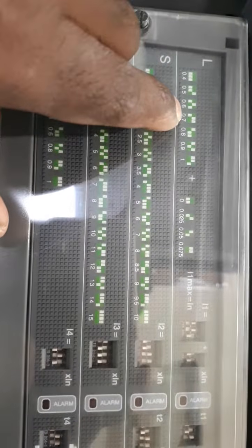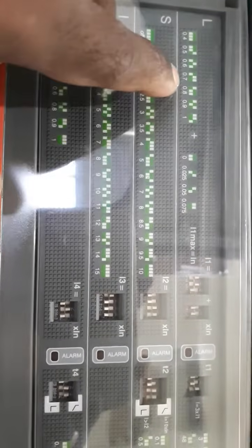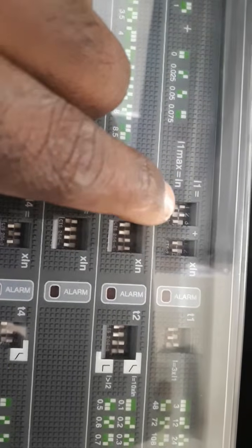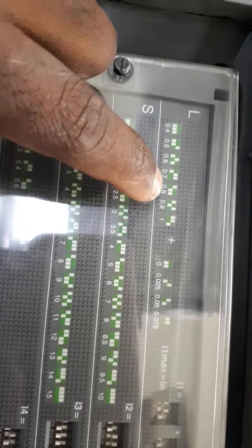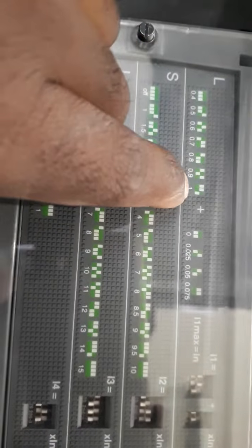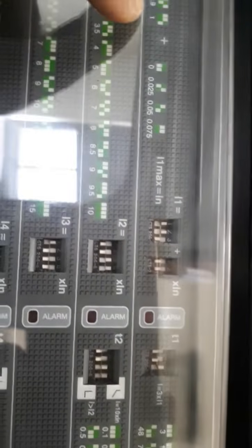Okay, IR value, this is. So first, here the position is knobs 1, 2, 3 are available. The first two knobs are in upper position and the last knob is lower position. So we can look here where this value is available. Two knobs are upper position, you look here, 1, it means the IR value setting is 1. Because it is the same position here, 2 knobs are upper position, 1 knob is lower position. It means the value set is 1.